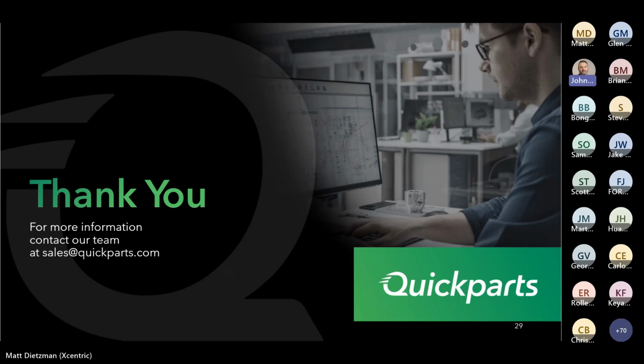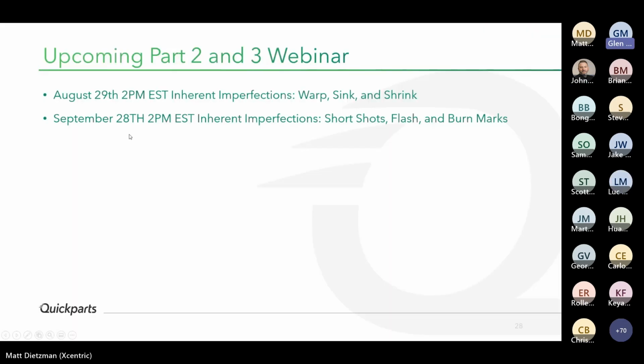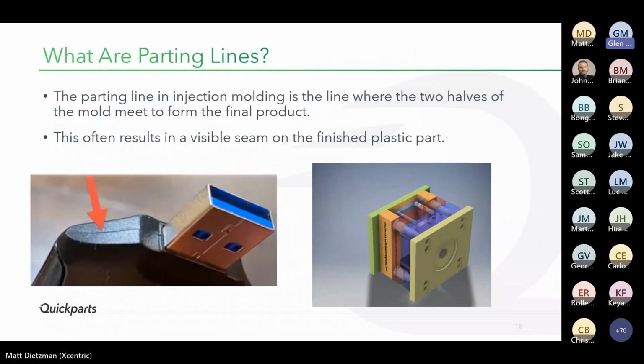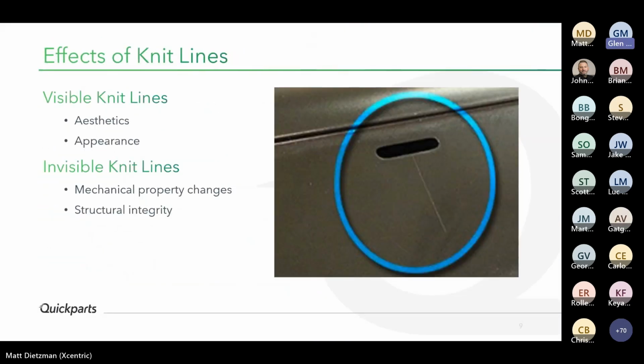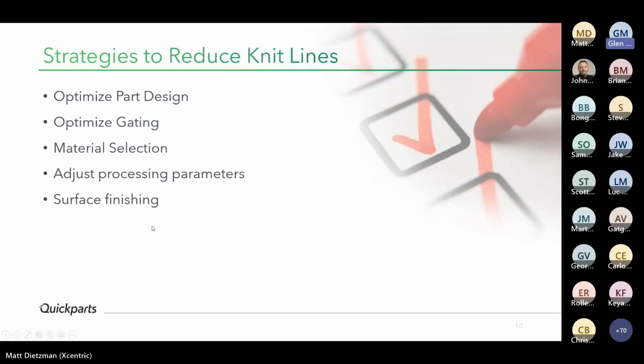All right. Next one: how can simulations help in mitigating the formation of knit lines? I'm assuming it's more about predicting it, right? Mold flow gives you a general idea of where your material is going to go and where the end of your fill is going to be. It's more about predicting where it is and then trying to adjust from there.